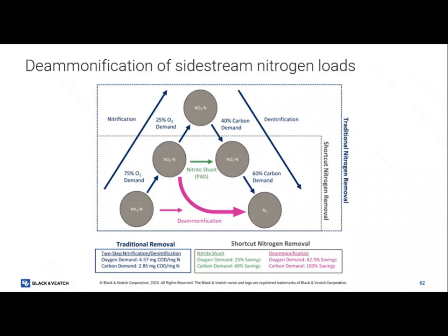What are some of the challenges you foresee? Think about your traditional nitrification systems in the mainstream. You're doing this process. Has anybody ever tried to stop here? You don't want to, first of all. Stopping here is very difficult in the mainstream. You're basically trying to say, I want to stop growing NOB, but I want to grow AOB. So I want to pick AOB over NOB.